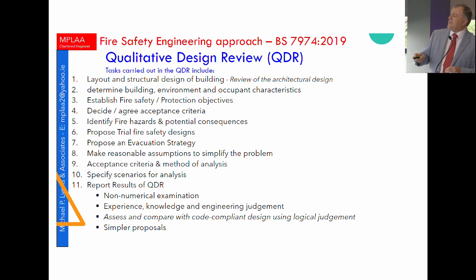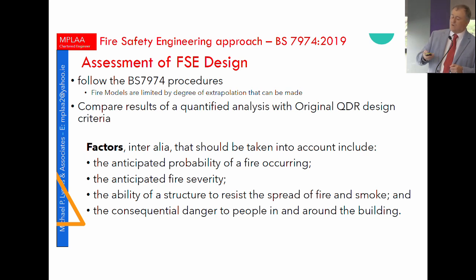You've got to specify then the different scenarios for an analysis to be shown to reflect that your fire safety strategy actually works. So you go through all your iterations, and you've got to be able to show that your analysis then delivers the tenability limits that you have to set at the very beginning, in the full knowledge that the assessing officer is going to agree with those. You want to make sure that they're going to agree with those tenability limits.